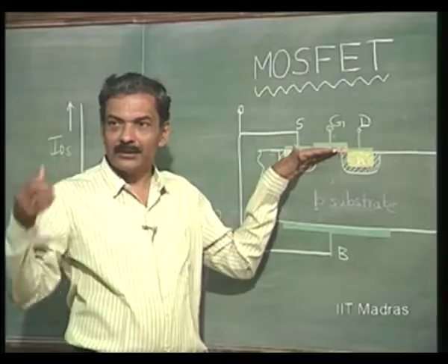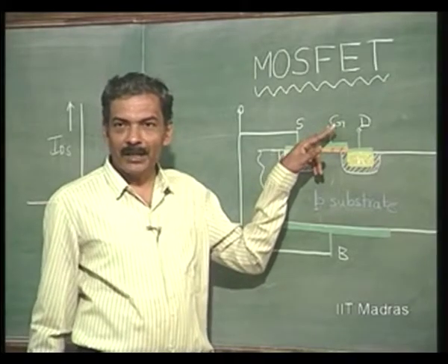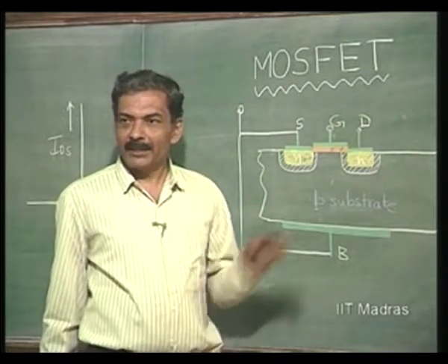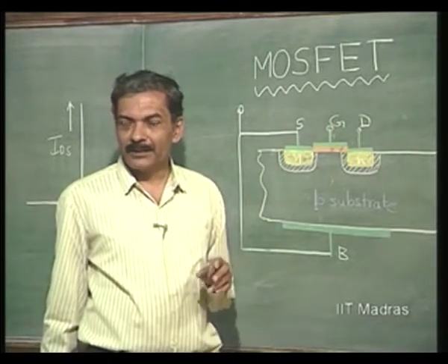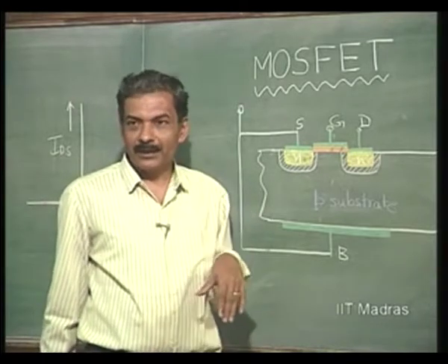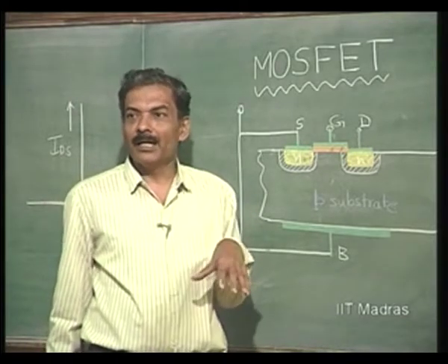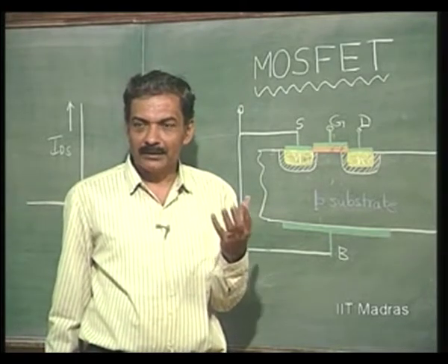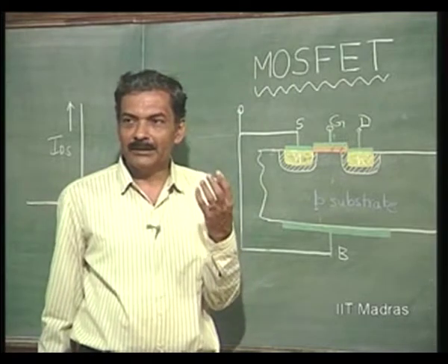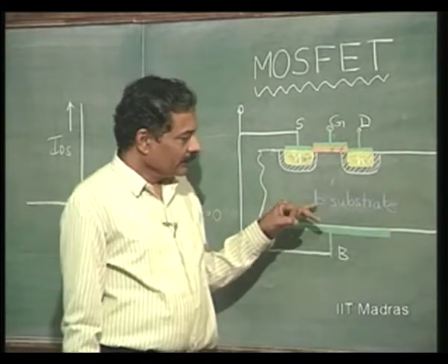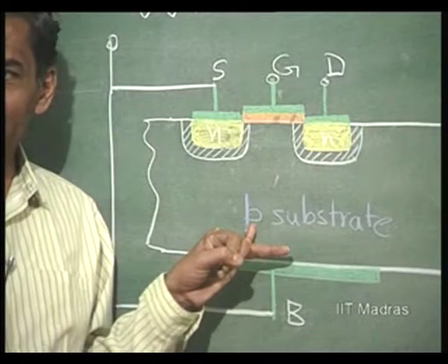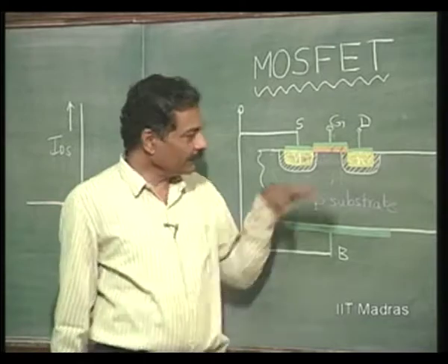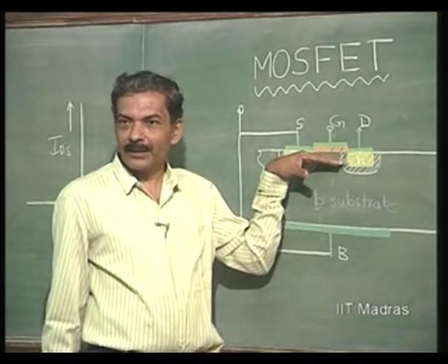Then as further positive voltage is applied, you have most of the minority carriers already coming to the surface, then you start to uncover the immobile atoms which carry charge. The impurities here donate a hole, therefore acquire a negative charge. So that way the negative charge is uncovered here.